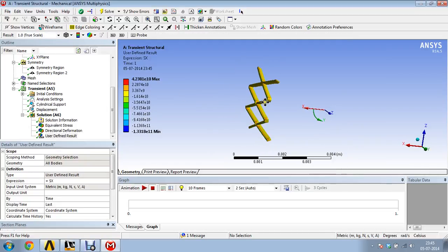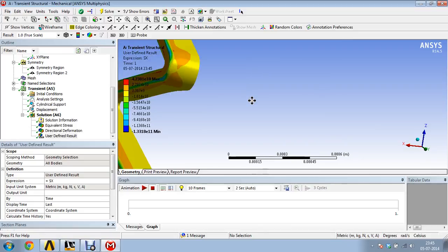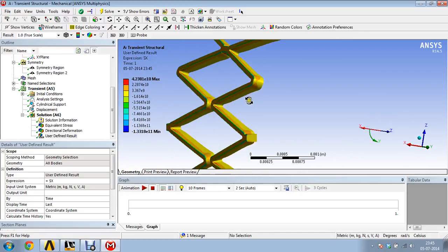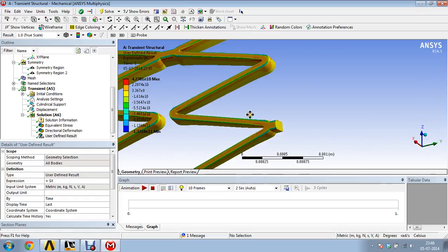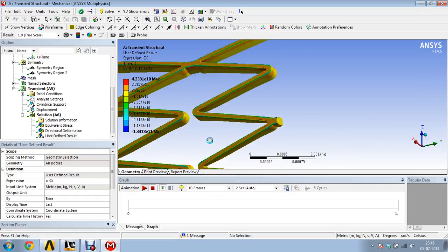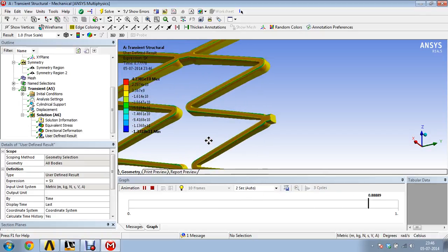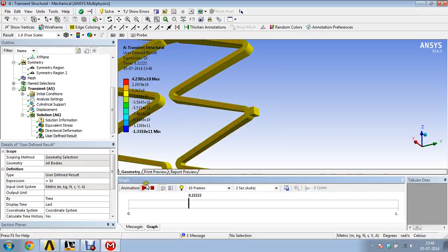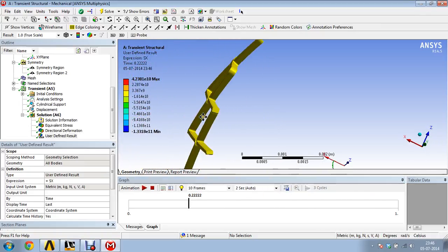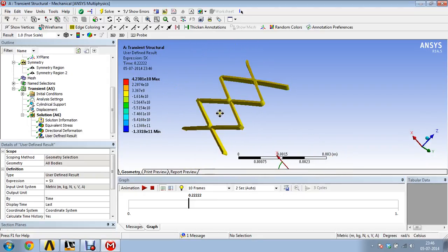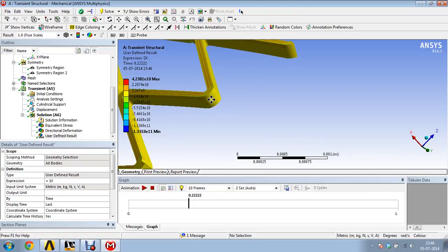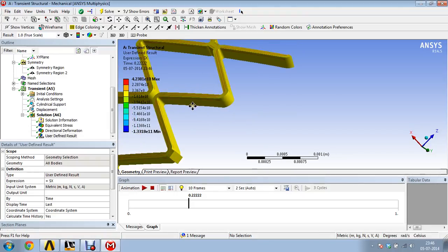So you can very much clearly see that throughout the thickness the radial stress is somewhat constant, and it only appears on this. Okay, so it is very much clear that because it is a thin cylinder kind of geometry with spaces in these parts, there are constant stresses in the radial direction along the stent.